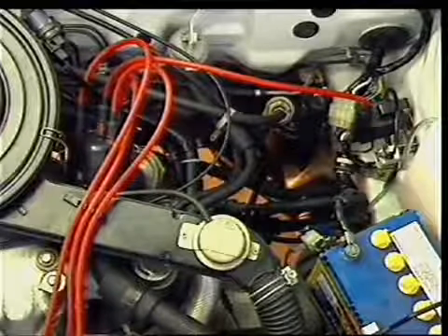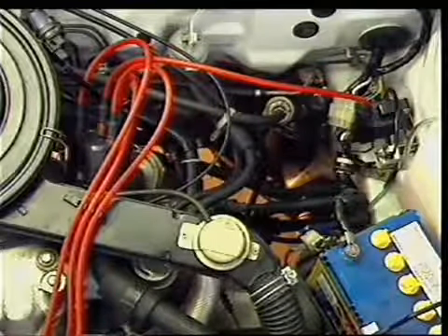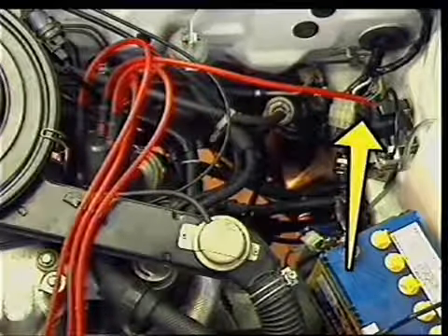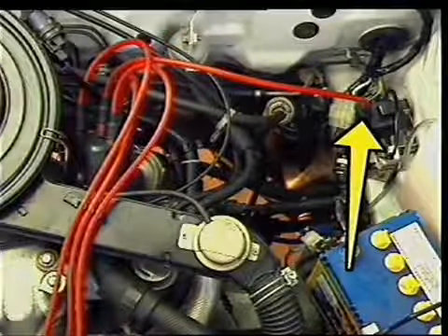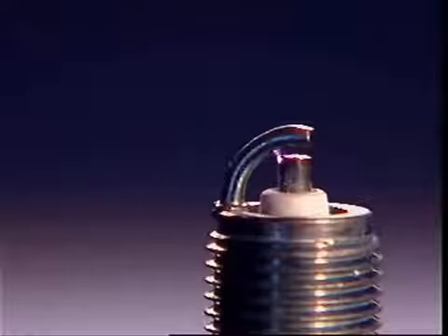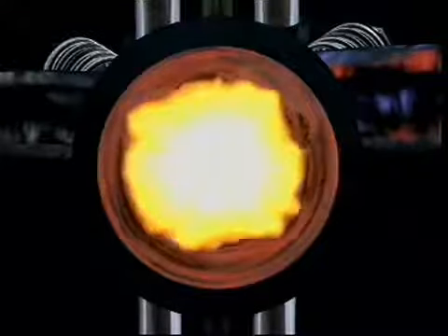The energy required can be obtained from the vehicle's electrical system, but the nominal battery voltage of 12 volts must be increased or stepped up to provide a firing voltage of many thousands of volts. This high firing voltage causes the spark gap to become electrically conductive, enabling an ignition spark to occur. It must have sufficient heat energy to ignite the mixture so that it can continue to burn by itself.